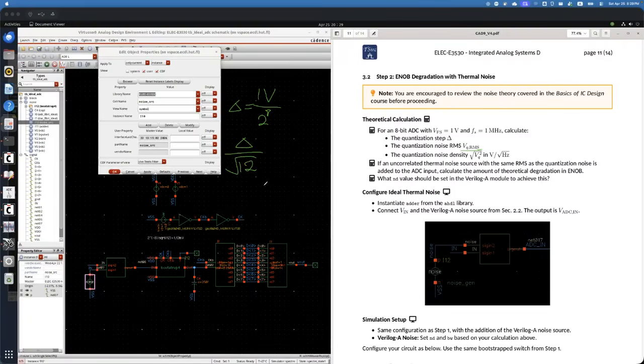And then this one is spread out in the frequency domain up to fs over 2, which is the Nyquist frequency. Those are spread out as a uniform distribution, white noise, not modeled noise. That means this one is an RMS noise, and if it is spread out uniformly over the frequency domain, then what will be the noise density?